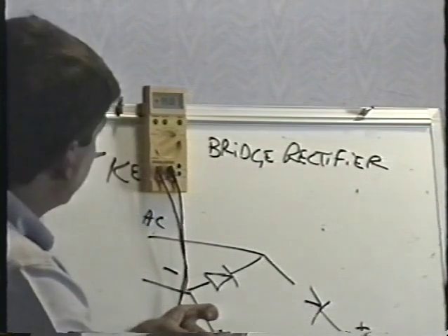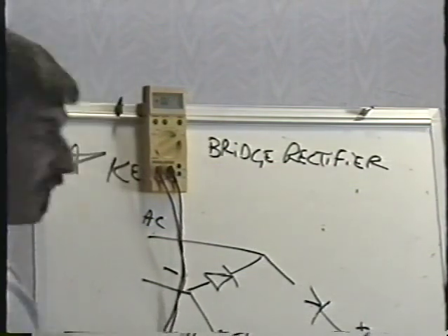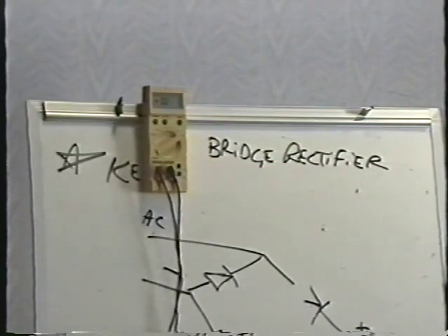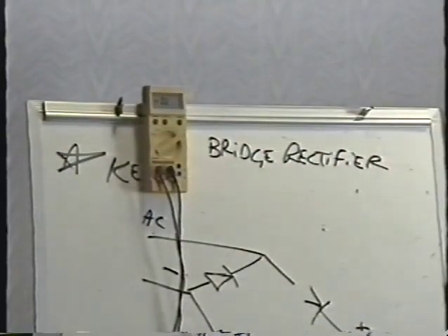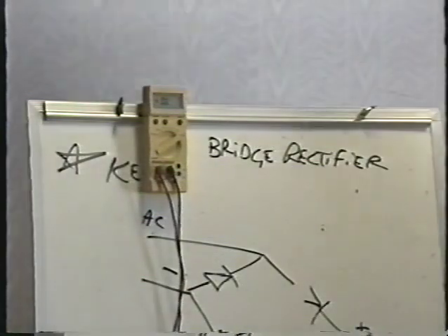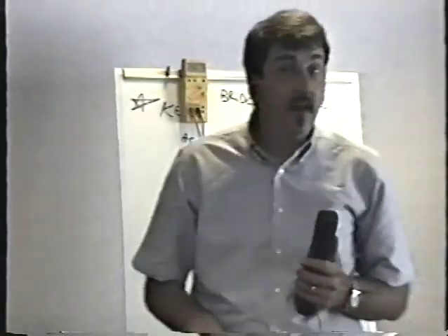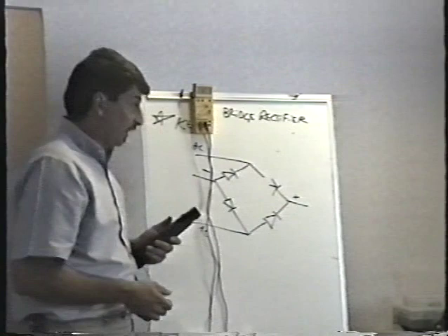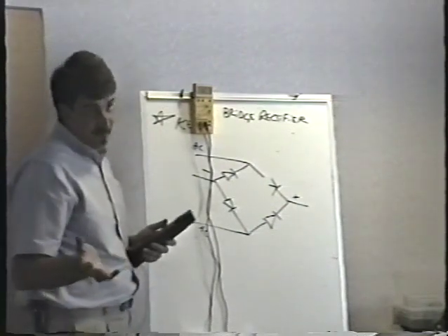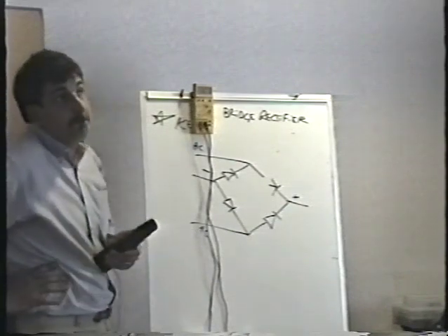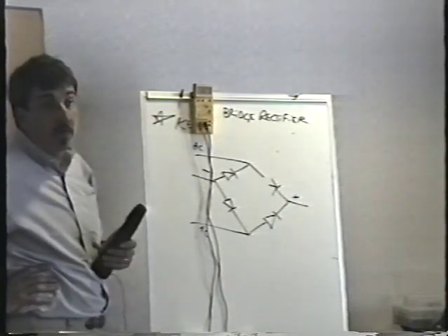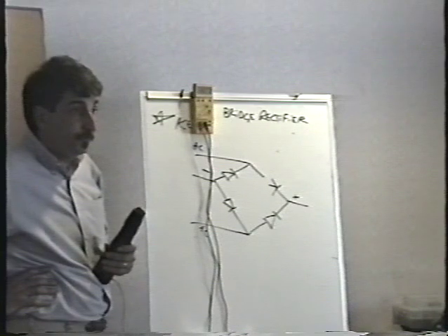That's interesting. I wonder where this one came from. So in this one, one of the diodes is open. That's pretty weird. But it certainly didn't pass the test. There's no question about that. So as far as diagnosing bad bridge rectifiers are concerned, it should not be a problem. It's pretty obvious. It's very unusual to have an open circuit. Almost always they short circuit, like the first one I showed you.